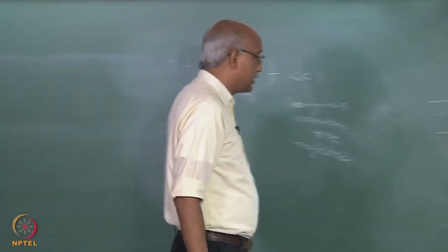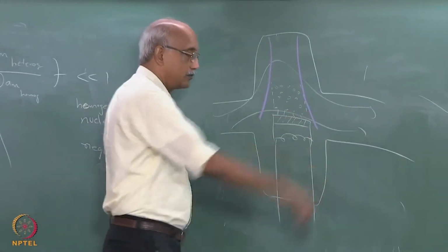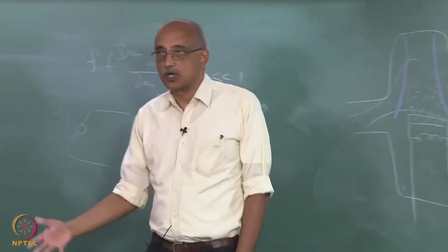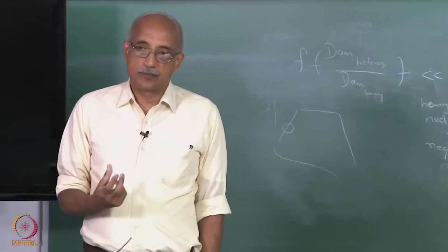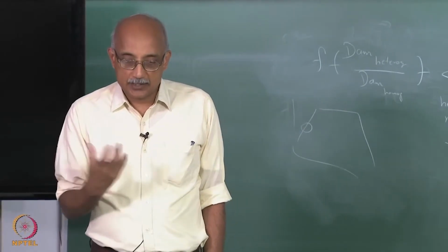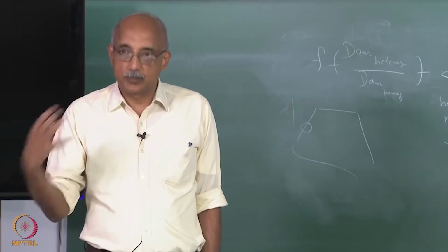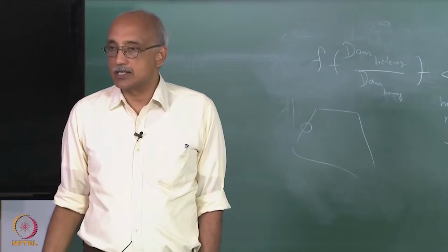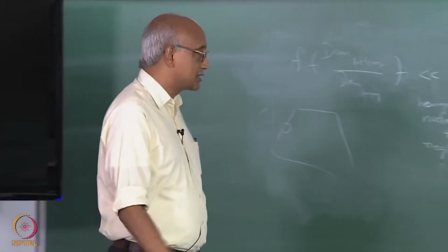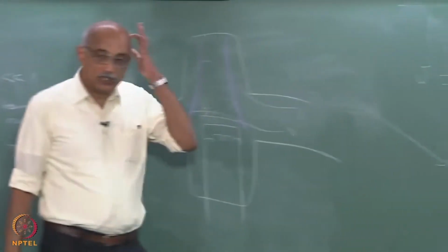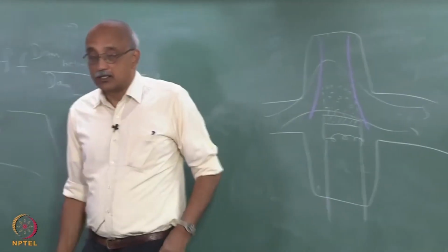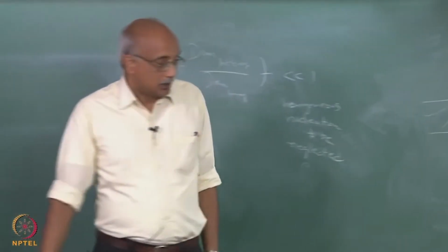It is very difficult for them to escape along with the gas phase, because they do not follow the streamlines. They have a sufficiently large Stokes number that they essentially act as a second phase, which is not coupled to the carrier gas phase. So, this inertial separation enables them to directly impinge on the substrate and form a layer there.